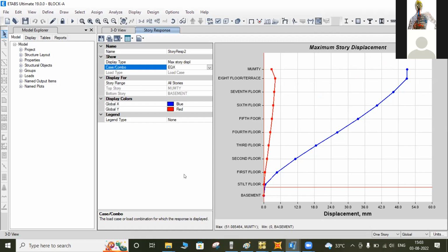Now I will go to some of the next topics. Karim, after analysis, we have to do the design, and we have to optimize the structure, right? When we perform the seismic analysis, we also move to dynamic analysis. See the dynamic behavior, check the story stiffness, frequency check, mass participation, a lot of checks, sir.